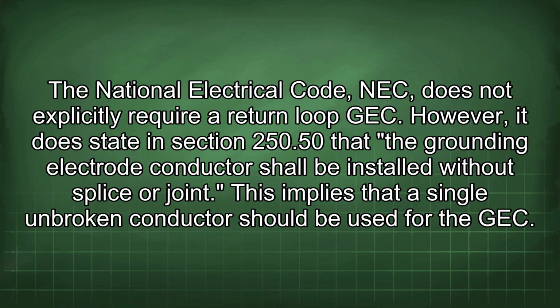The National Electrical Code (NEC) does not explicitly require a return loop GEC. However, it does state in section 250.50 that the grounding electrode conductor shall be installed without splice or joint. This implies that a single unbroken conductor should be used for the GEC.